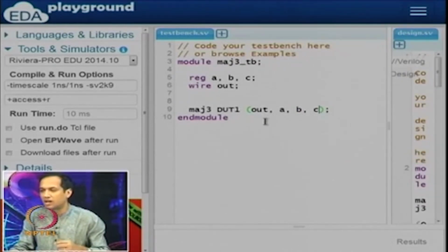By accident you do not want to connect an output to a voltage supply and an input to be connected to an oscilloscope and so on. So what I have done is I have declared local variables here which are supposed to be connecting to VDD or ground and whatnot, and I have maintained the order in which the design is expecting the inputs and outputs.